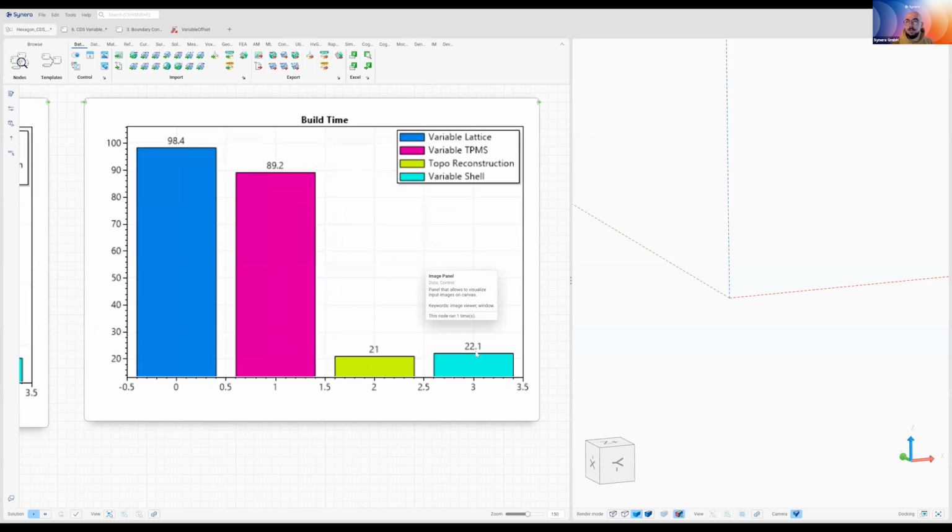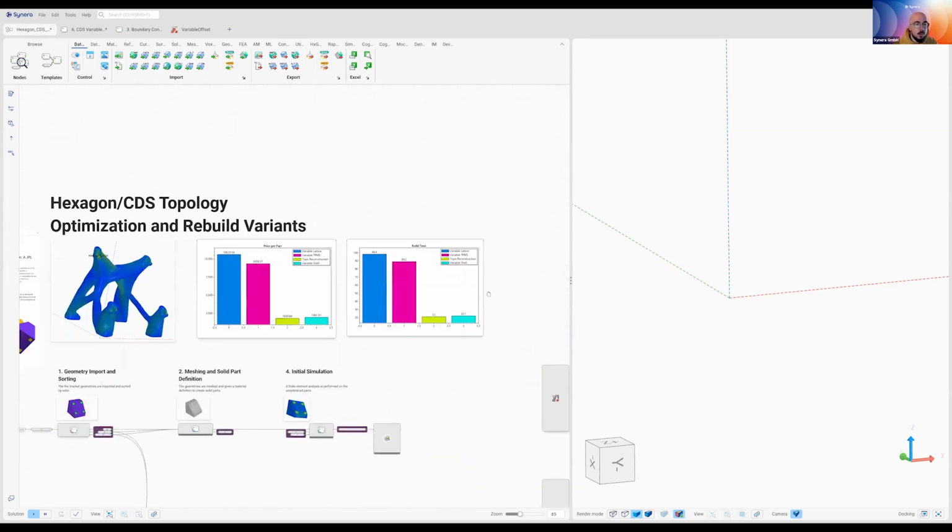Now, obviously, depending on your use case in additive manufacturing, you may have different constraints. For, let's say, an aerospace application like this bracket, you may not care so much about cost and build time. You're much more concerned about the end weight of the part, as that greatly impacts the cost it takes for that to go to space. If we're talking about an automotive component, well, the build time and cost are going to be much more applicable here, driving constraints for you, because obviously if you're manufacturing 100,000 components by additive manufacturing, you need to drive the cost down. And so what do we have for a workflow?